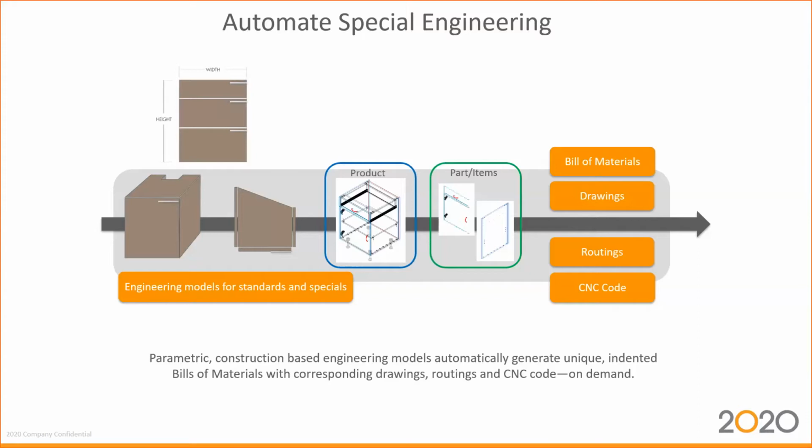And based on which kind of machine you have, if it's a nested-based router, if it's a point-to-point machine, if it's a dowel insertion machine, we are generating basically for those machines a final CNC program. And the operator can then easily scan the barcode, call up the CNC program, and execute that program directly at the machine. So no manual programming necessary at this point in time.